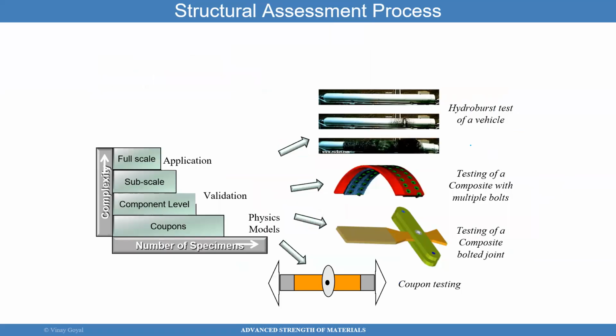So in real life, for composites particularly, you have to do a lot of testing at the coupon level and build confidence at this level before you go to a more complicated system, where if you were to fail, you lose millions of dollars. But if you learn your lesson with more samples at a smaller scale and you validate your models one step at a time, then once you get to this point of a large scale test, you're more successful.